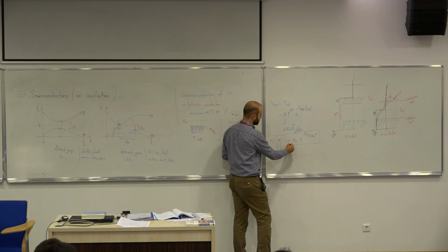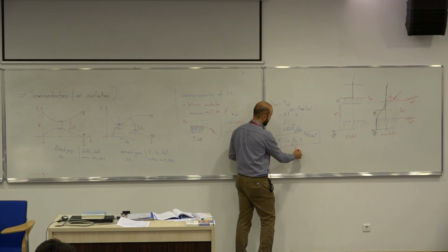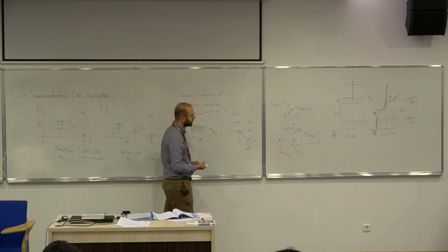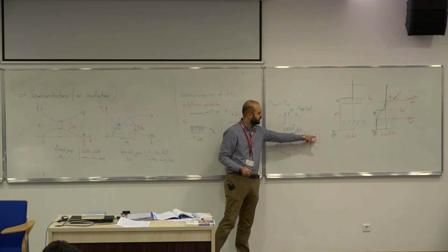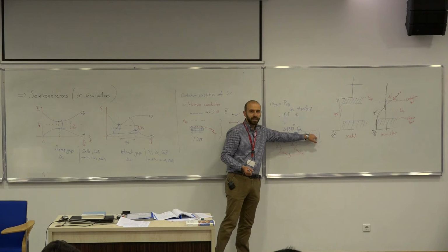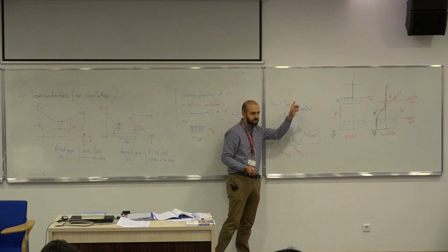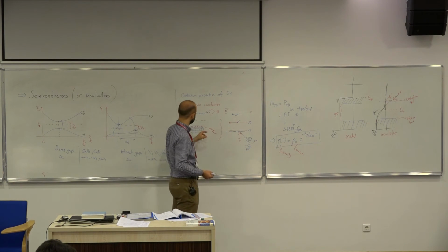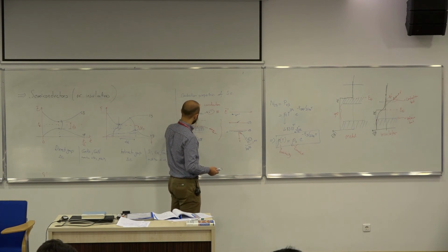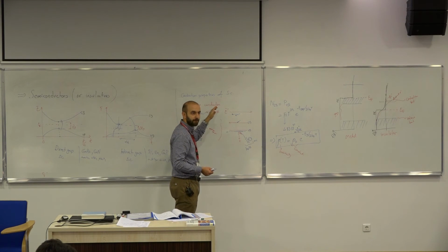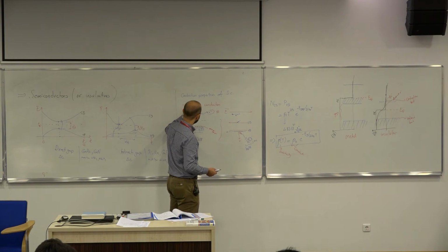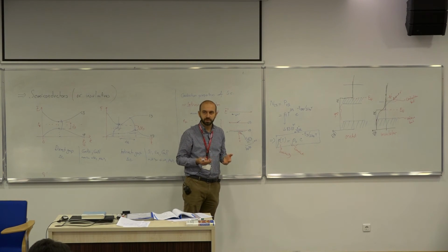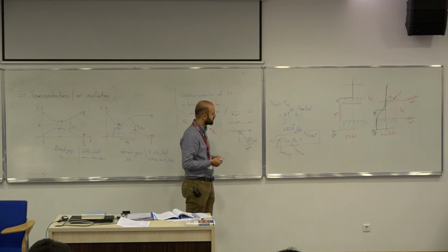This is some constant. So resistivity of a semiconductor depends on the temperature. And as you increase the temperature, resistivity decreases, because that's somewhat expected. The distribution will spread out even further, and you will get more and more electrons and more holes. So the overall expression for the resistivity will be something like this.